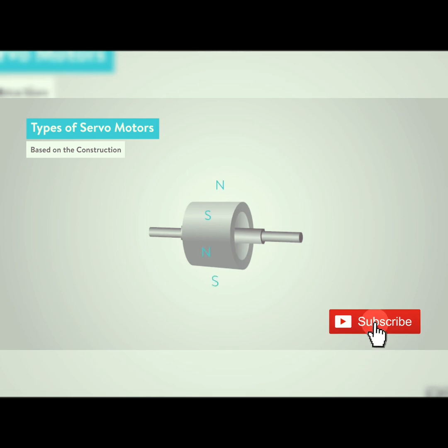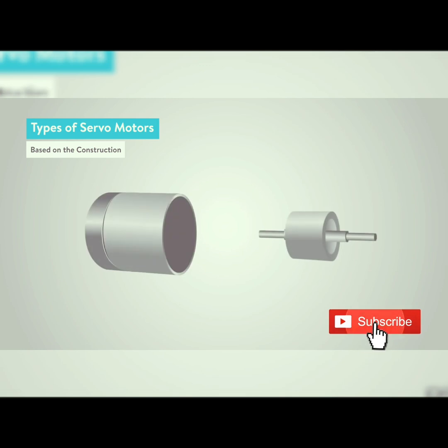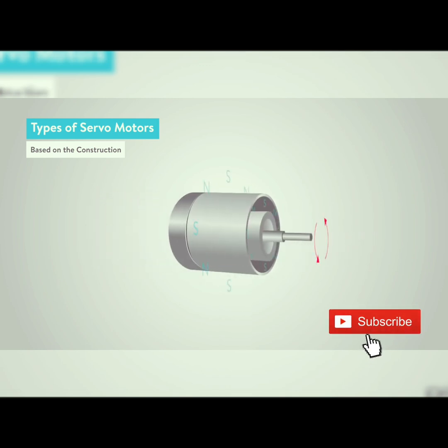The rotor consists of a permanent magnet, and this differs from the asynchronous induction type rotor in that the current in the rotor is induced by electromagnetism, and therefore these types are called brushless servo motors. When the stator field is excited with voltage, the rotor follows the rotating magnetic field of the stator at the same speed, or synchronized with the excited field of the stator. And this is where the synchronous type is derived.